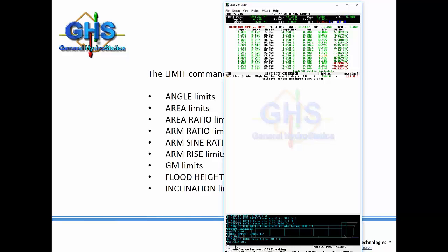So 200%. And indeed we are failing because at 10 degrees, perhaps I should cancel. No, doesn't matter. My righting arm at 10 degrees is about 0.087, and at 20 is 0.327, which I would expect it to be valid. I think I would need to disable the wind. Right. Okay, I would need to raise in absolute righting arm. This is absolute righting arm. So at 10 degrees it's 0.21, and at 20 it's 0.492. Yeah, but 200% means I was looking at 100%, but it's actually 200%. So I would have to have at least 0.6 meter.